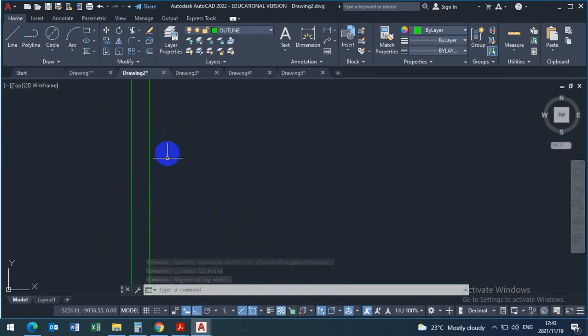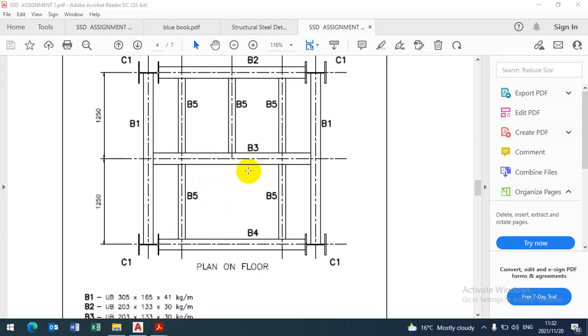Okay, and then I think we need now to do beam 3, and then to do detailing of beam 3. This is the top view, because we said the beam is going to be notched, being that it's going into the web of beam 1 here. We need to notch the beam here. We are not going to show the notch from the top view, so this beam 3 will show the detailing from the side view. We'll be looking from here where we see the flange and the bottom flange.